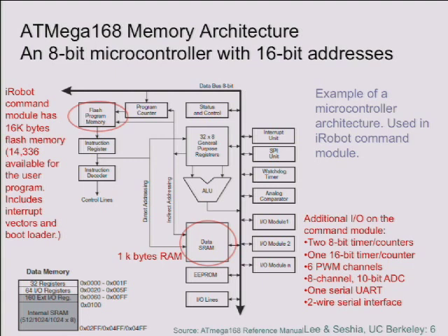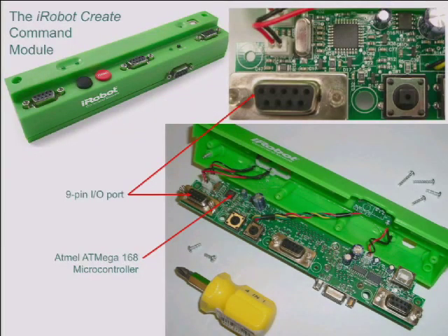If you have an error in your C program and you start reading from memory that doesn't correspond to physical addresses, all kinds of interesting things can happen that will make you scratch your head and you won't be able to see what's going on. Because there's no printf statements on this. Where would a printf go? You could write code that would talk to the serial port, and you could connect up a terminal to that serial port that would read the data.